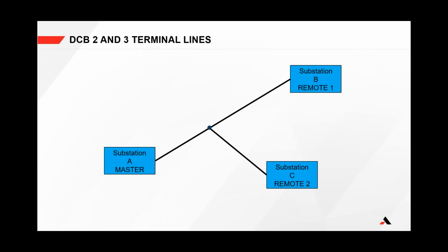For this example, we would stay with a 3-terminal line, which also covers the 2-terminal end-to-end line scheme. There are two methods for addressing the individual UPLC, coded or timed. When using the timed mode, low-level blocking and high-level blocking signals are keyed for a single pulse of specific duration.